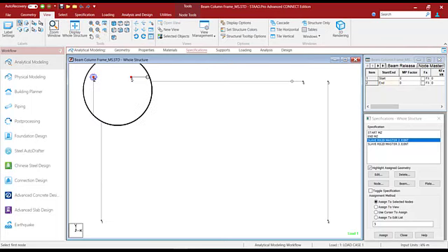So we can see that node number 2 has been highlighted in a peculiar way, where it has been encircled with two concentric circles. This is an indication that in the master-slave relationship, node number 2 is the master node. And we can see that node number 5 has only been plainly highlighted, which means that it is a slave in the master-slave relationship.